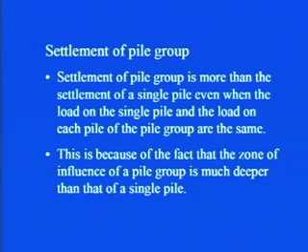See, when it is in a group, obviously when the load is coming, it forms a larger bulb of influence zone as compared to a single pile. That is why you get more settlement of the pile group, because more soil strata is contributing to the settlement. So, the more the soil strata, the more the settlement.